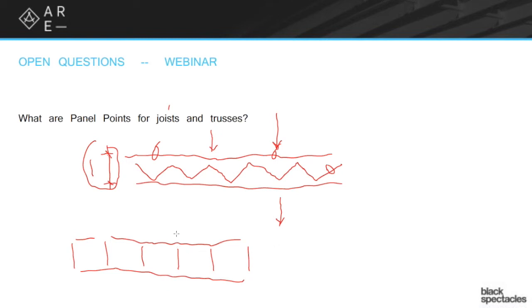The reason I mention it is that you still call these panel points, and there's still a reason why you might want to load on those direct panel points, having to do with spreading the overall load. But the main reason I mention it is that whenever you talk about trusses, the Vierendeel truss is one of those weird ones that has a very specific name, and therefore you can often get a question about it. It's worth just knowing what it is, but also knowing that it's not a real truss, right?